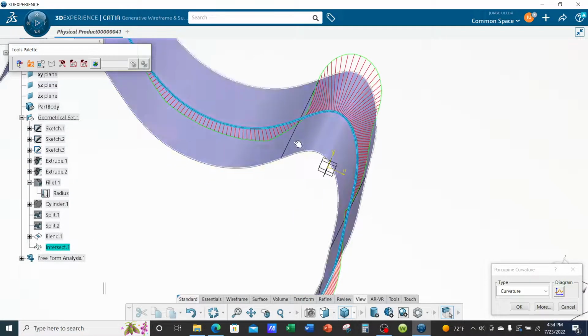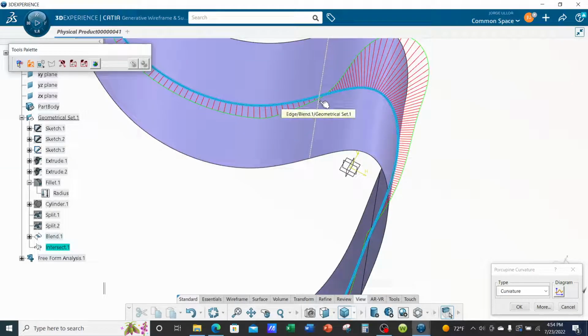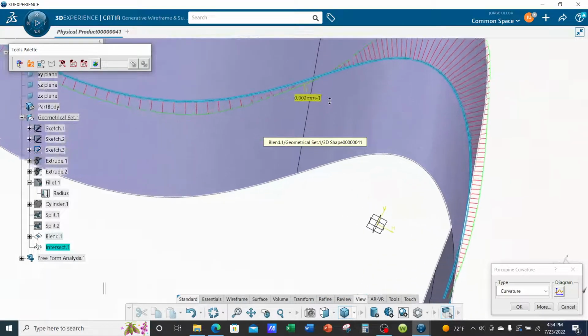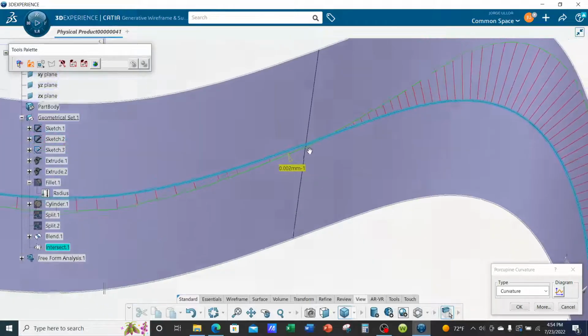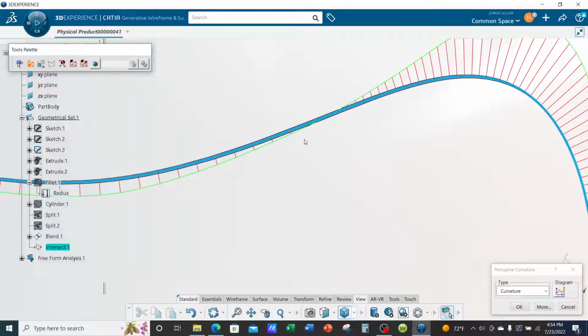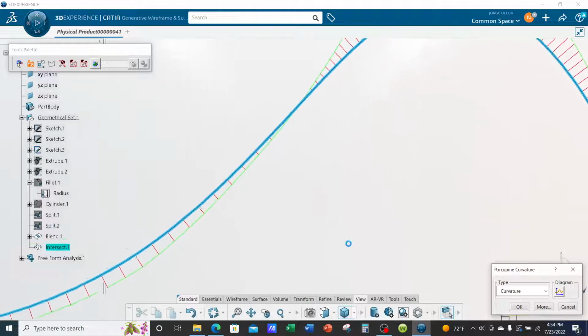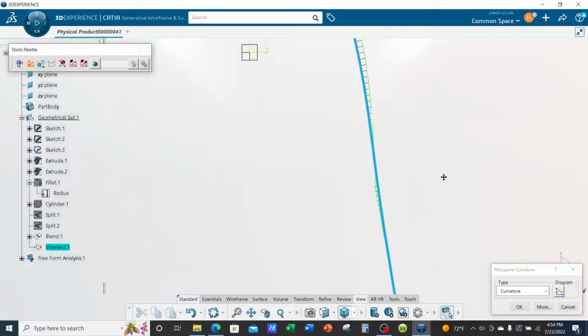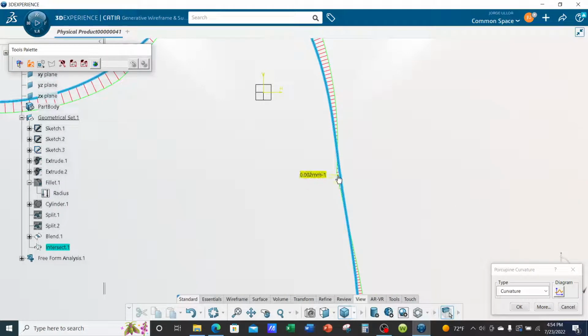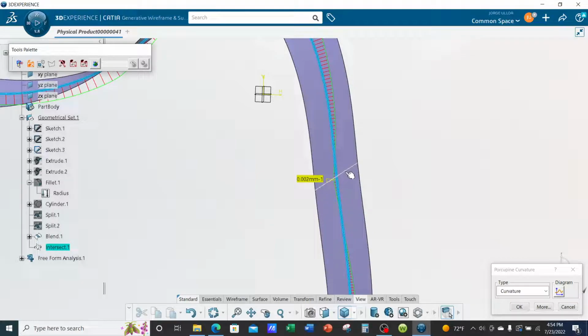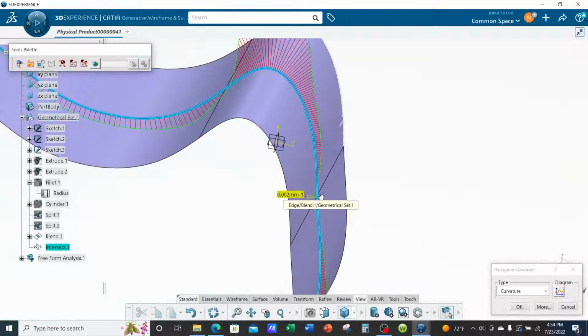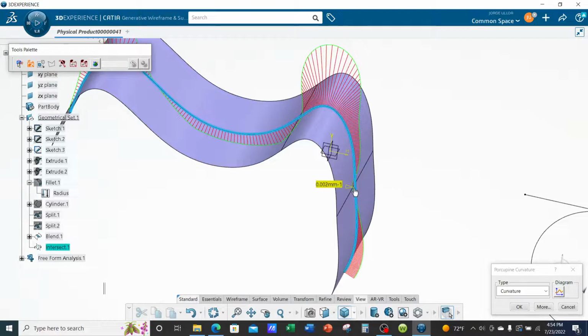Okay, so you can actually tell where there's a transition change on the Porcupine. It almost looks like a little disruption. It's not as clean as the rest of the curve. Let me go into front view. It's not as clean. Same thing on this one. And that's where our seam lines are. That's where we have our transitions. So again, we can improve on this if we have the option to go up to a G3, which in this case we don't. But it's still good enough. It's still clean enough.